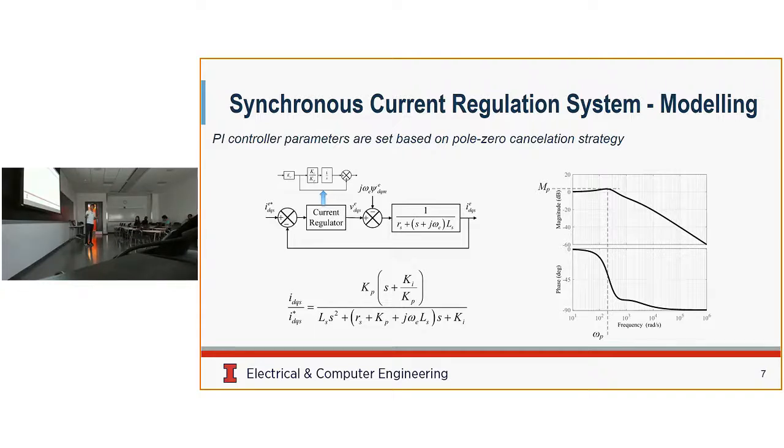So this transfer function is a little bit different from the conventional transfer function that we normally know, because you see that some coefficients have an imaginary part in them. But we can use the well-known methods to analyze this transfer function, like the Bode diagram. And you can see that this system will not be just a normal second order system.